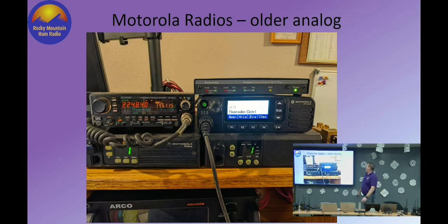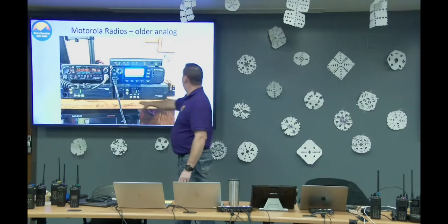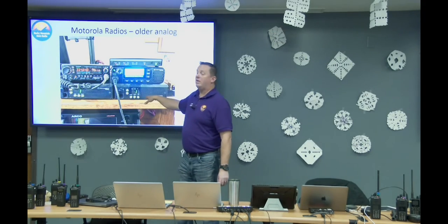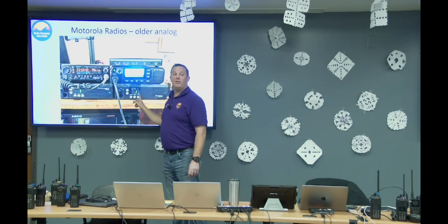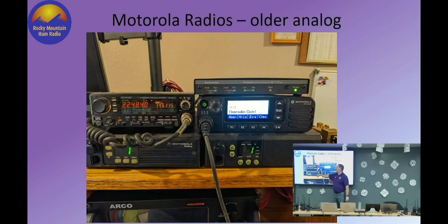They make really, really good packet radios. Matter of fact, in my home shack, I have a Radius and a Radius GM300 and a Kantronics, and I have those three wired. This is my 1200 baud VHF, my 9600 baud UHF, connected to the same TNC, and that's what I use for packet and Winlink and things at my home station.